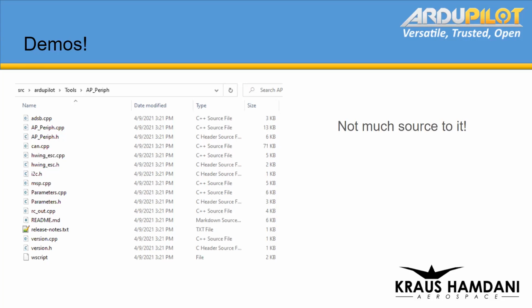Yeah, it's not high bandwidth, right? It's 38K, 56K, but that's what OSDs were before we integrated them on board the chip. They were MAVLink dongles. So you can get almost everything a normal person would want in an OSD with the MAVLink telemetry.